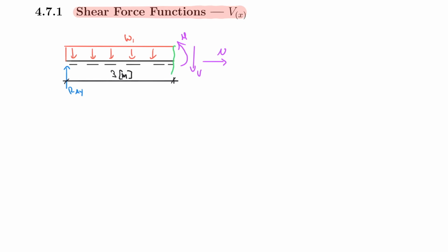But today I want to take it to a different level, not a finite level, but an infinite level. So I want to describe everything in terms of x along the x-axis, so that I can describe the shear force and later on the moment in terms of x. So what I really want to do here is describe the shear force as a function of x. Let me erase all the other parts here that I'm not worried about in this section. I will later worry about the moment. For now, I just want to focus on the shear force.